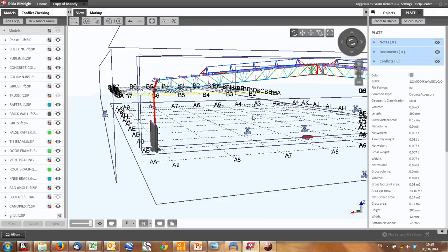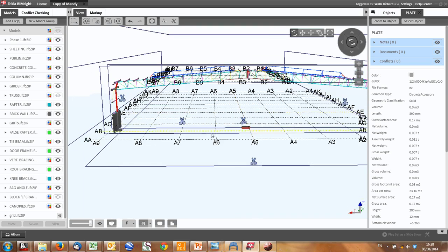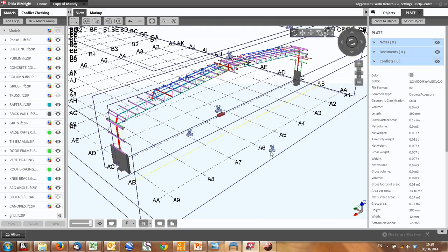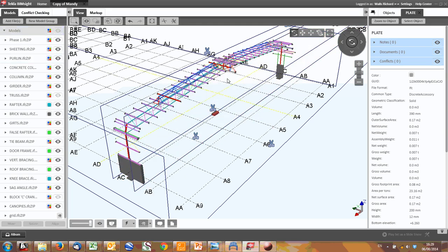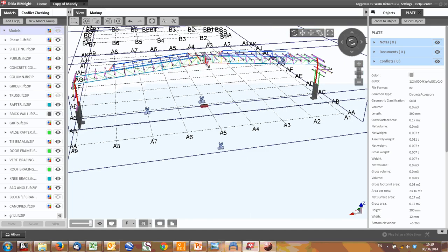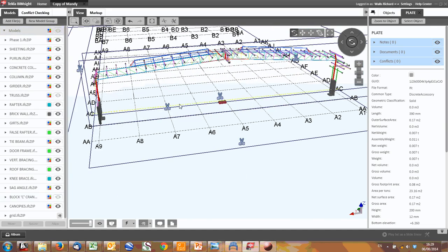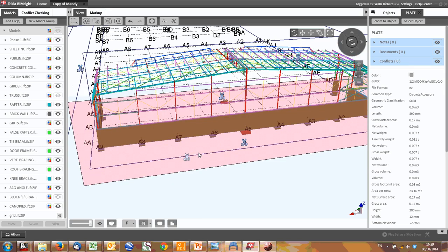I think this was a 3-degree slope. Normally 5-degree leaks less, but the architects quite like 3 degrees because it gives you a much flatter roof. Alright, so that would govern then the spans, obviously how much area you need, so that would influence what system you use. If you can have more columns, you obviously have shallower trusses.